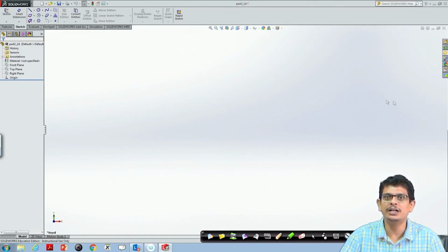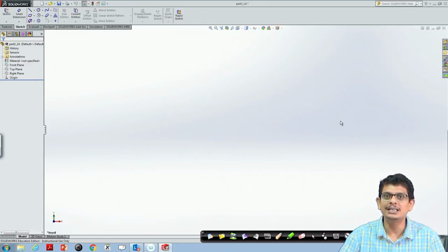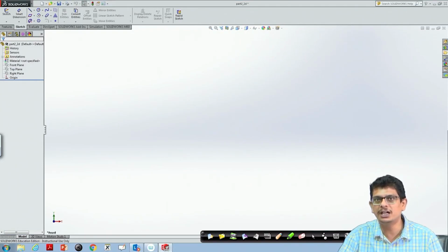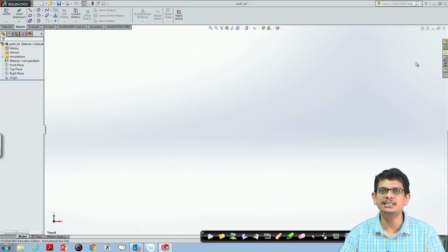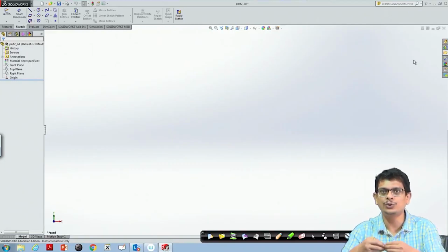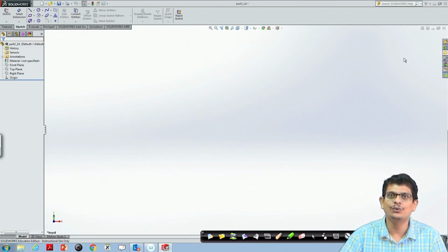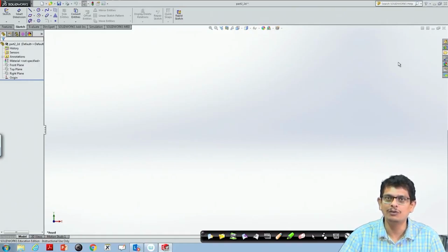So, it is always recommended to come out of sketch mode, then save the drawing, and later you can reopen it. In this sketch mode if you saved it, and after that, without coming out of sketch mode and saving it, you click the mark, it takes the recent version that you have already saved. Now, if you are trying to close the drawing, that means do not save anything. So, it erases everything. So, one has to be careful even at saving the drawings at regular intervals. Always come out of sketch mode, save the drawing.